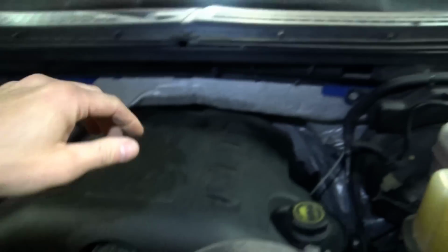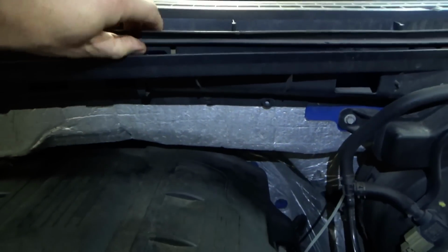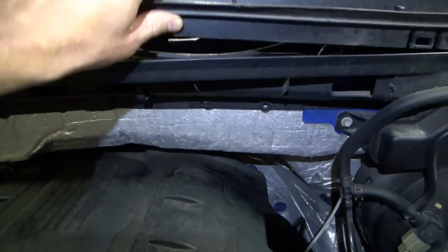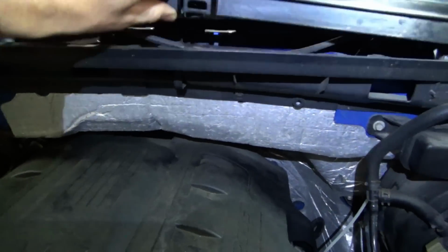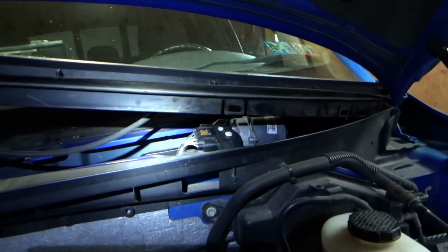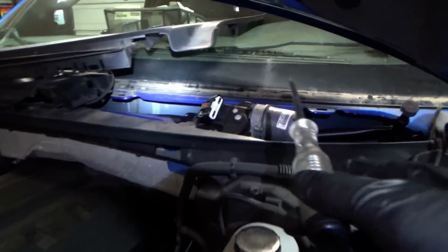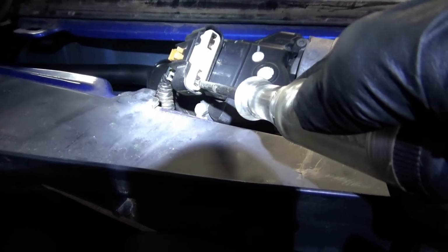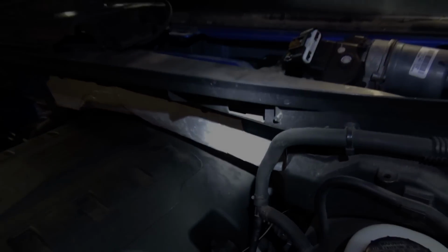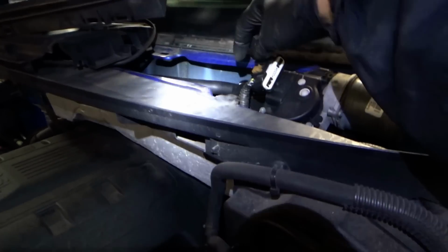So next, let's go to the wiper motor assembly. Perfect. So the guy already has the cowl torn apart. Let me get that off. You see the wires right there. Alright, so we got a test light connected to battery ground. If I find a positive, it's going to light up. Here's our violet and white wire right here. So, no power.